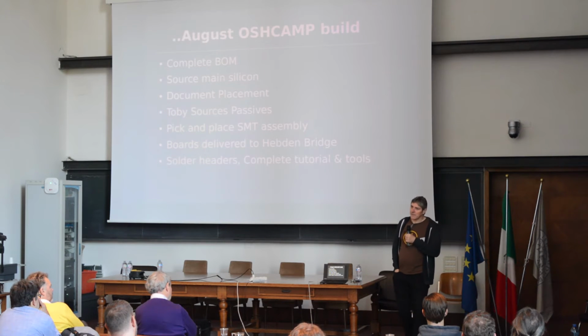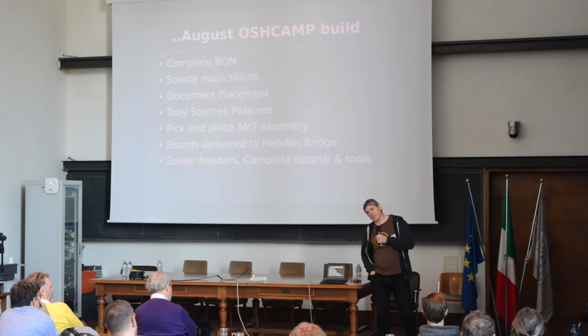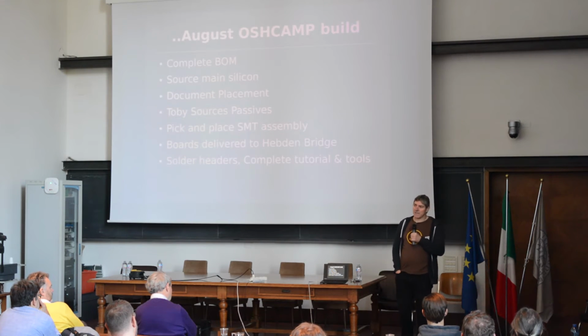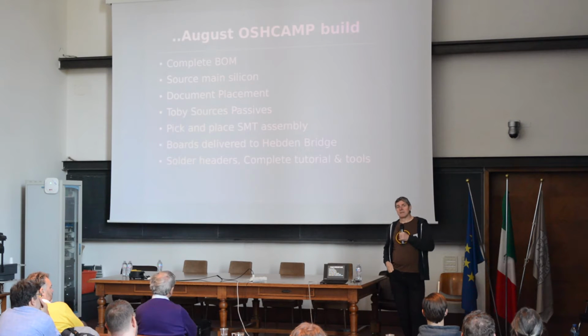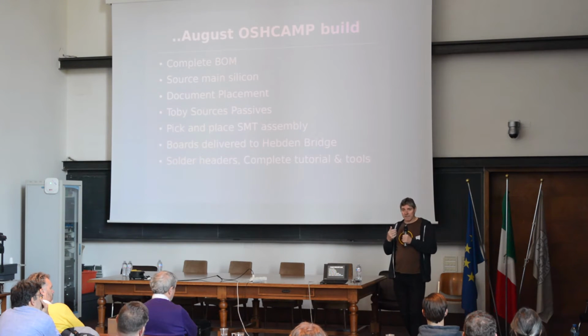Of course, in doing so, you set yourself the problem of, oh, well, now we have to work out a way of getting the ARM chip to get the information to the FPGA, the Lattice FPGA. So we basically chose a larger ARM chip that has a lot more flash, that is capable of actually holding the bit file, the bitstream file, and we actually inject that into the Lattice ICE product in a slave mode over SPI. But all of that software had to be run.